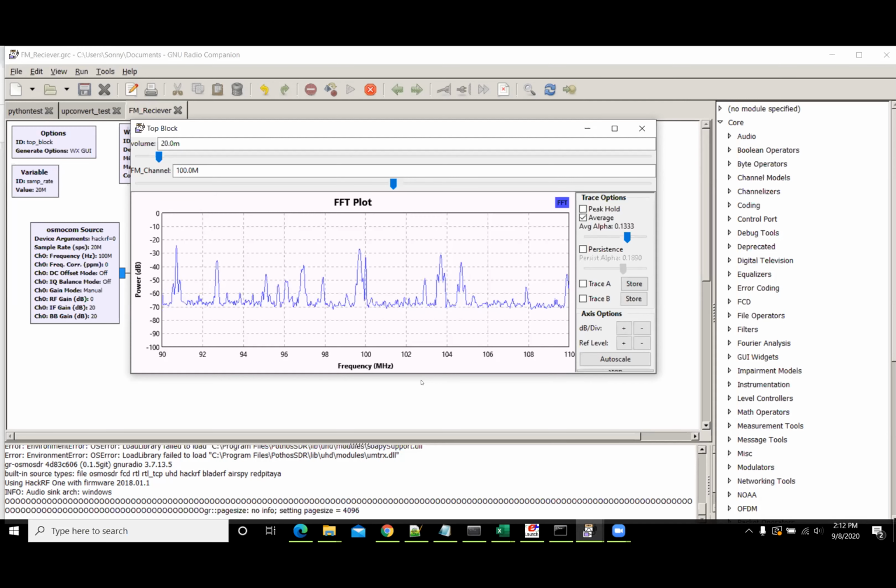What is transmitted over the air is a sine wave. That sine wave is frequency modulated, meaning that its frequency is somehow varied by some audio signal. When we were listening to 99.7 right there, whatever that voice is basically gets transferred onto the frequency of this 100 megahertz waveform, transmitted over the airwaves and picked up by this radio.